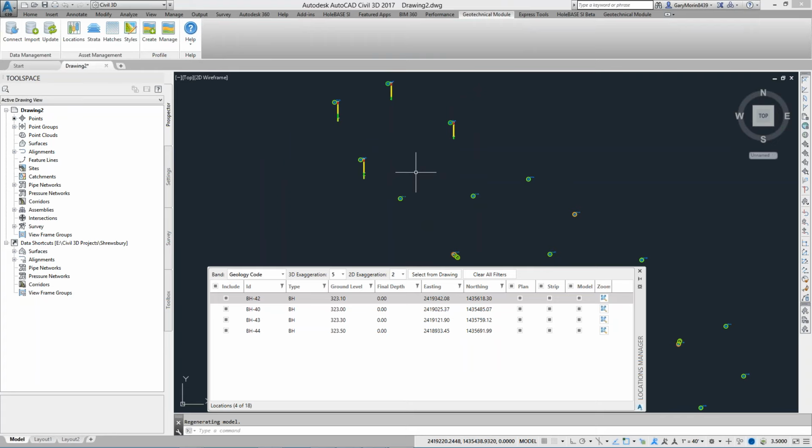We also have another option. If you imported the data and you suddenly realize, oh, that's the wrong data, or I really don't like the look of that data I've just imported, perhaps these 4 boreholes we've just looked at here, we don't like the look of, I can click on this button here to say, hey, don't include them, ignore them, pretend they don't exist, okay? And any work we do from now on will just ignore those boreholes. But at a future date, I could just bring them back if I wanted to.